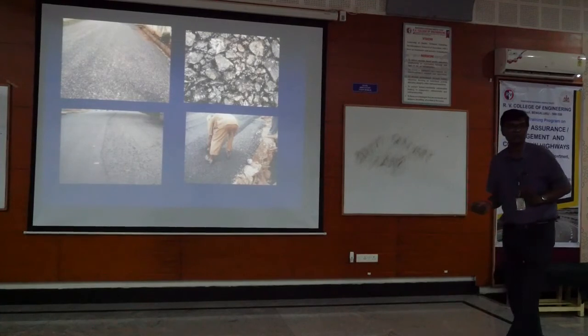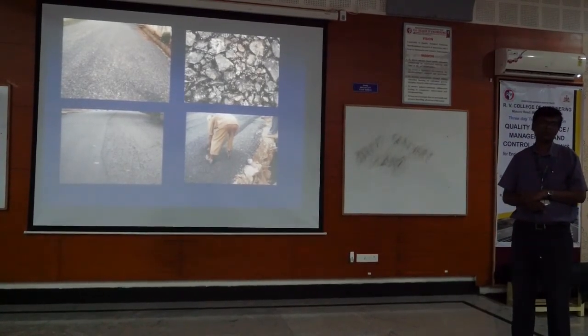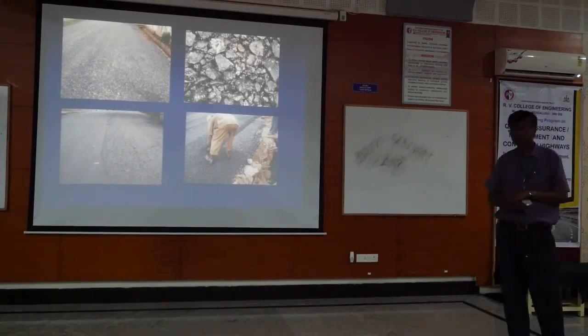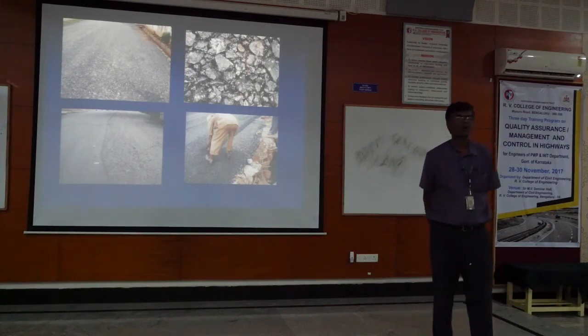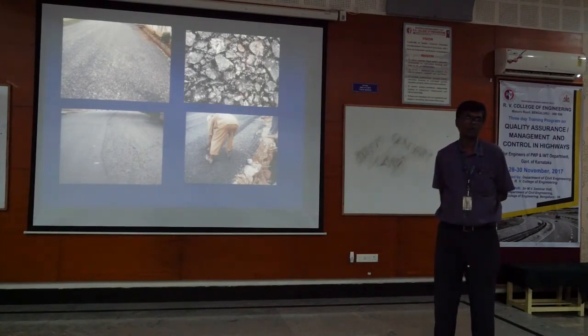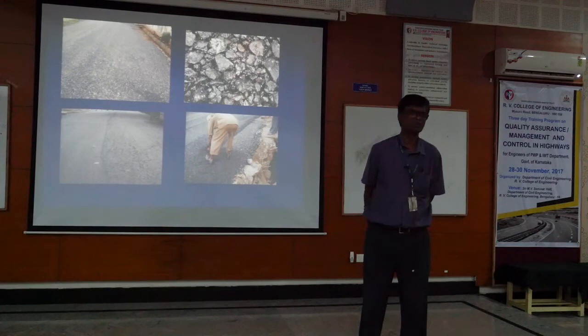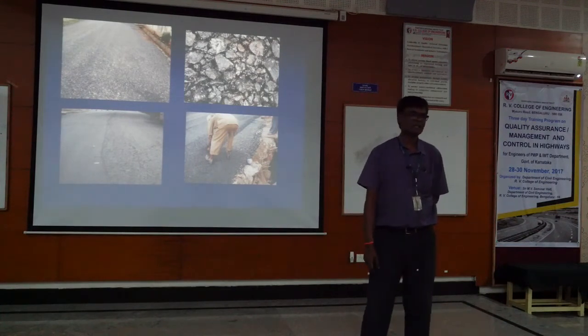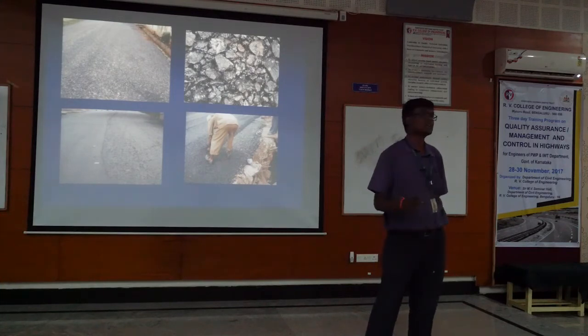At the time of construction, especially for this wearing course, how do we ascertain that the required degree of compaction has been achieved? For other layers we can check after laying, maybe 1 or 2 days or even weeks, but this has to be ascertained instantly. So the best method is if you can insist that the contractors use rollers with compaction gauges. That's possible, it hardly costs anything. Almost all compactor meters with rollers are given on demand.